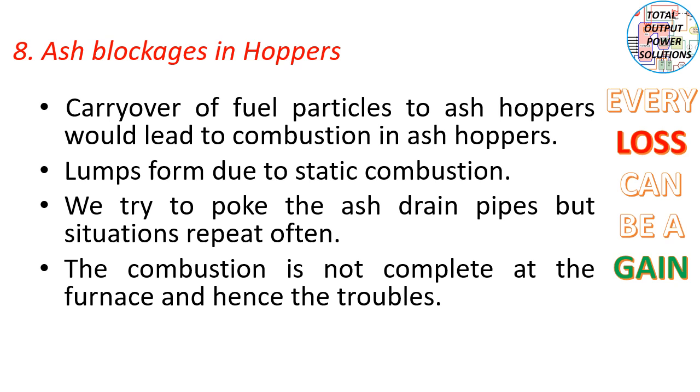Then ash blockages in hoppers. Carryover of fuel particles to ash hoppers would lead to combustion in ash hoppers. Lumps form due to static combustion. We try to poke the ash drain pipes, but the situations repeat often. The combustion is not complete at the furnace and hence the troubles.